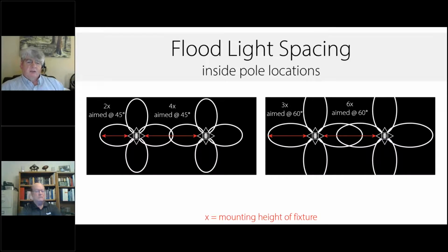Sure. So similar to what we were talking about with the area lights, you're going to light up the center of a parking lot. You've got large areas that you're going to try and light up, 30, 40-foot poles or whatever, and you're going to put multiple floods up there. Again, you're not trying to tilt these things up 60 degrees or 70 degrees or 80 degrees. You're trying to just get nice uniform spread from a high source, and the flood might be what you have the most output in.